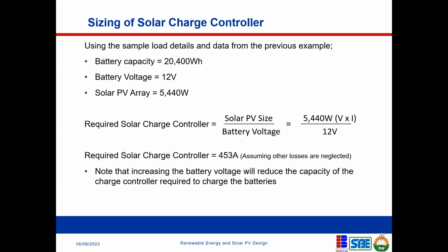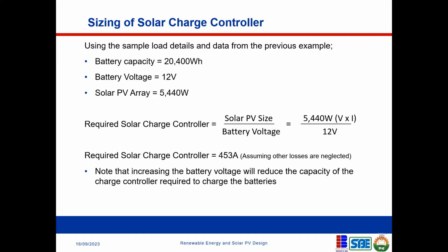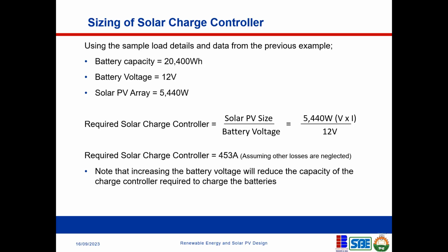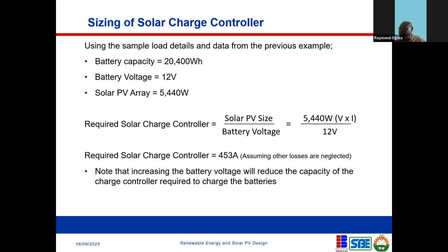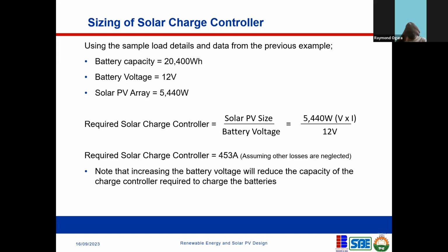Do we have a chart from which we can choose? So if you have so quantity, this is the matching controller, etc. Do you understand what I mean? No, not clear, please. Can you explain further? There are charts you can look onto if you have, say, 400 amps. You can go to cable ratings and see which cable can handle it.